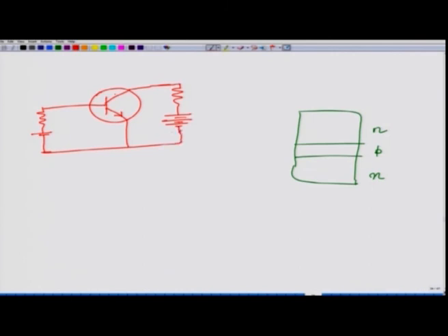Okay. We are talking of this circuit here, and the working is that when you forward bias this, you have a lot of current, a lot of charge carrier injection of majority carriers. So, this injects a lot of electrons across this depletion layer, across this junction here, and most of them are collected, let us say, by this collector. Therefore, you have a corresponding current. Then you also have a little bit of current through that base.